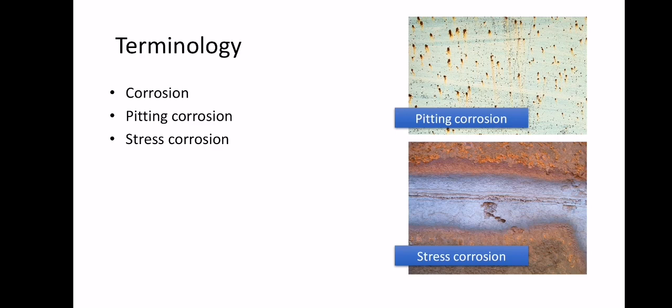The second thing is pitting corrosion. So it is a corrosion. The special thing here is that it happens at a dot. So this is problematic to metal. Why? Because you have this one point where you have all the corrosion, so it's going to pierce inside your metal. For example, if this was a tank, it's going to leak. If this was a pipe, it's going to leak. So not good.